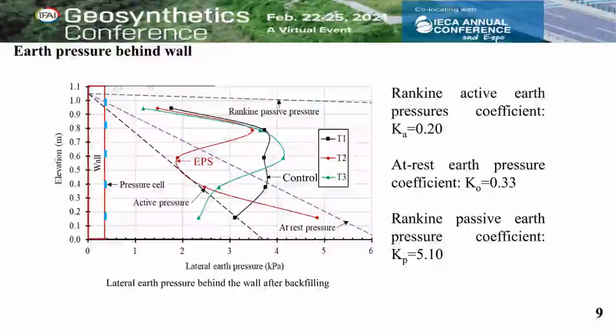The lateral stress near the bottom will be smaller than the at-rest pressure. The reason for this phenomenon is that the wall moved away from the backfill. Therefore, the lateral stress near the bottom will decrease.